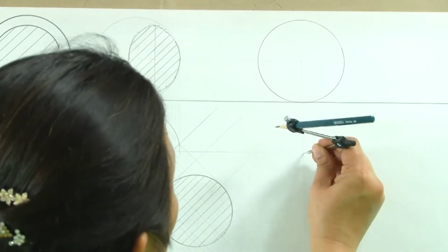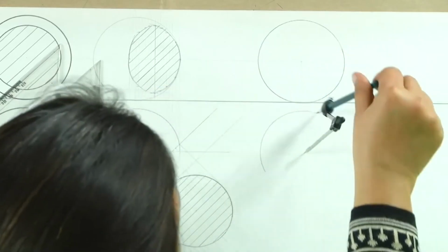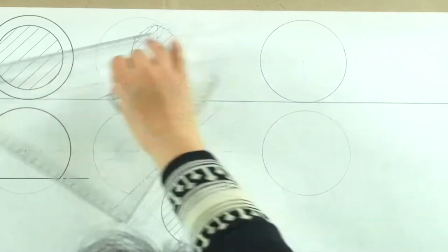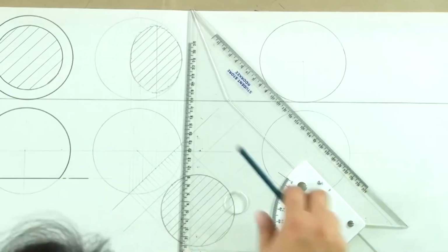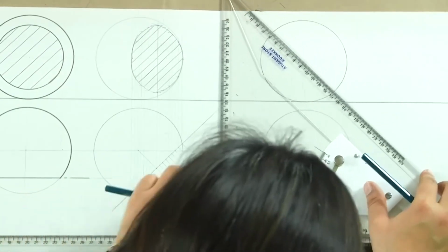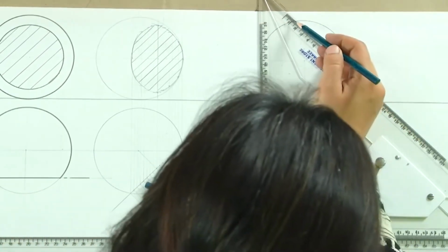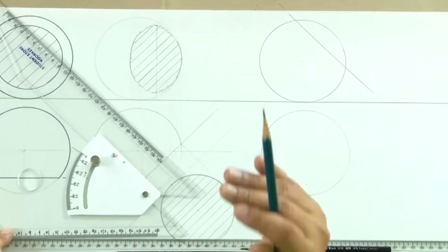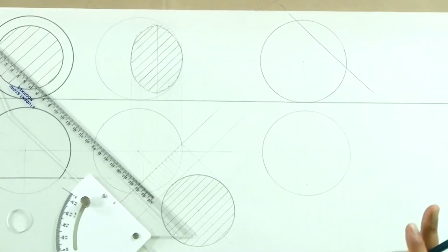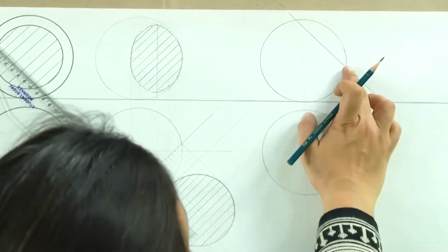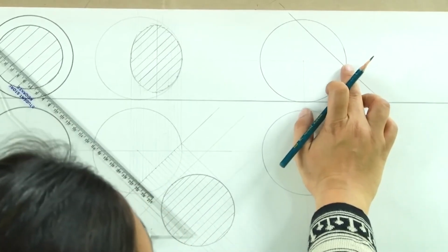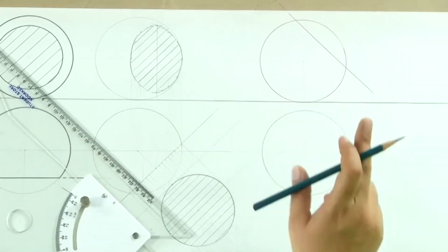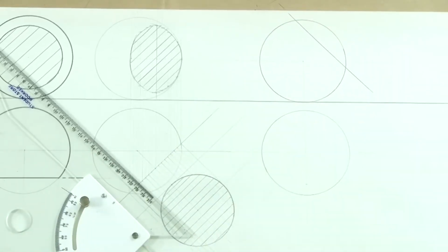So what are we doing? We are again starting to draw the original position of the sphere, which is this. And now I am just assuming that this plane is inclined to HP and it is perpendicular to VP. So what will we see? We will actually be seeing the true shape of this section in an auxiliary plane, which is parallel to this section plane. So we will always start by drawing it.